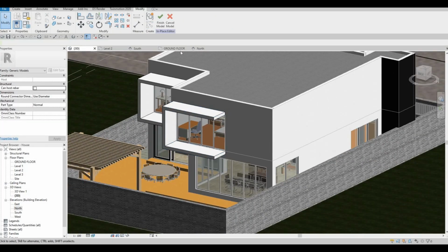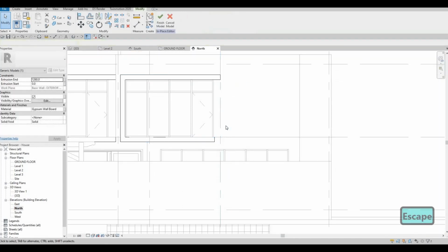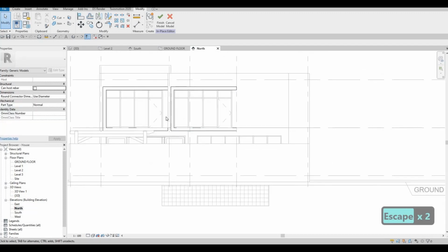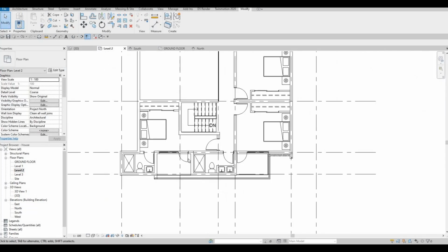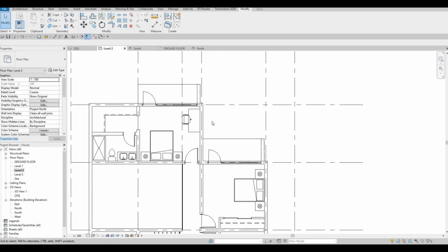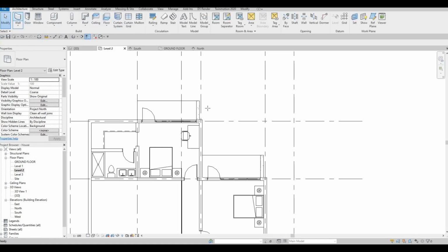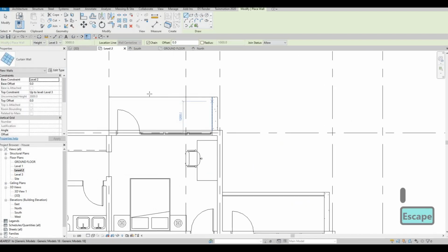And obviously what we need to do is just add a little bit right here, because we need to add some railing, and I want it to connect to the wall to make it nice. So now go back to level 2. So click on finish here first, go to level 2, and here we could expand this if you want to. You can make it longer if you want to as well, but we just need to add curtain wall, flip it on the other side, and then here as well.